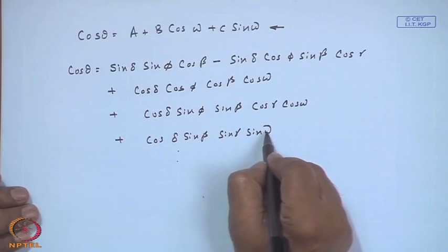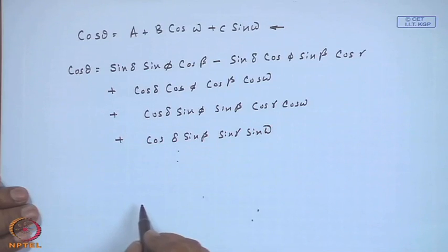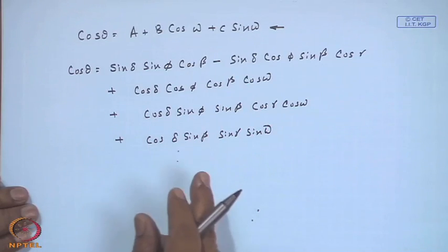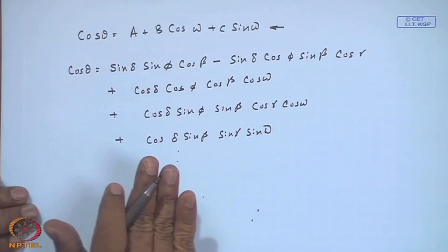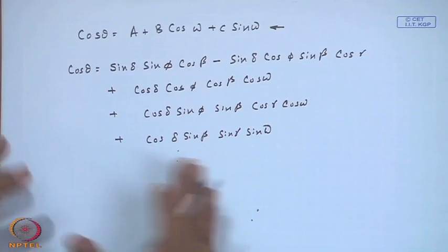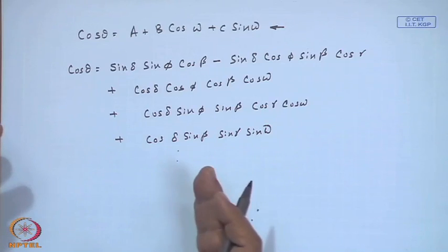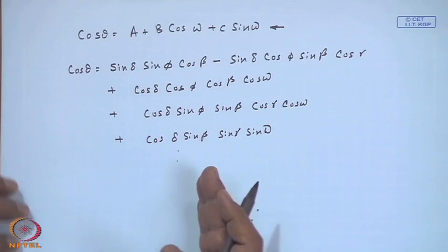Now, you know of course what A, B and C are. I am not going to spend a lot of time writing again what A, B and C are. So, we shall state this is the equation which will take care of whether it is south facing, vertical or horizontal, or any gamma, beta, delta that you can give. Delta, which we have already calculated as minus 20.34 for January 20th.